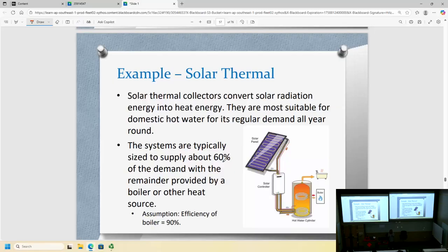And this heat energy, which is low-grade energy, is very difficult to transfer to another location. Then it is a wastage. So in order to balance the space required for installation and the heating demand, usually we will design it to meet 60% of the maximum heating demand.